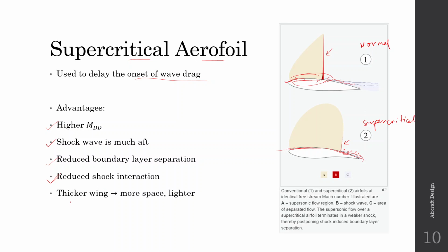And this is a byproduct of the supercritical aerofoil, but it has been observed that supercritical aerofoils are thicker. When they are thicker, there is more space inside for putting fuel and electronics, and structurally it is also easier to reinforce.